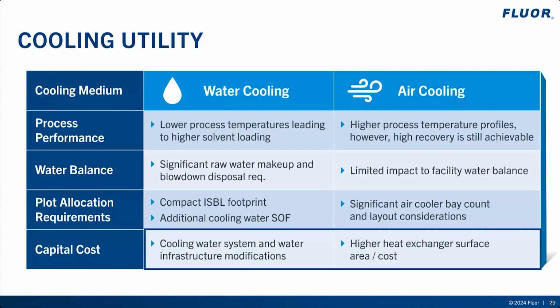Water cooling can provide a significant capital cost advantage when compared to air cooling. Improved heat transfer associated with water cooling reduces exchanger surface area and associated material requirements. For cold climate applications, air cooling winterization requirements can further increase cost differential associated with air cooling. Subject to cooling water design considerations, further addressed on the next slide, using water cooling in place of air cooling has the potential to reduce the overall capture plant capital cost by 10 to 20%.